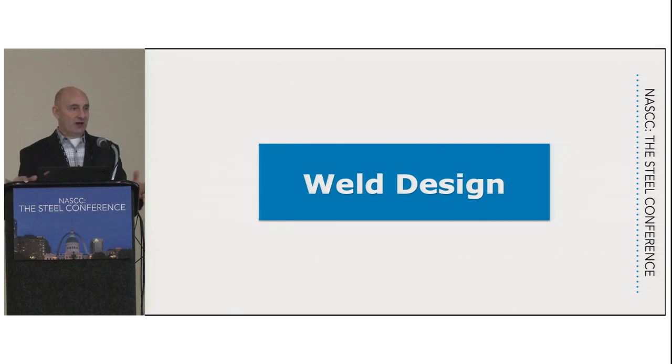just for a normal column, not a stepped column or a reinforced column or anything, if you want to check to make sure this method is accurate, you can put it in and go through all of the steps that I've just shown, and you should end up with something extremely close to the AISC equations that we went over at the very beginning of this presentation for flexural buckling. And the reason is because these equations, especially that reduction equation, were meant to simulate that. So it's basically a way to simulate that column curve.